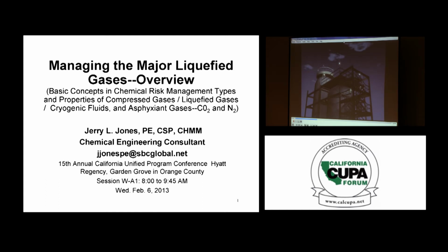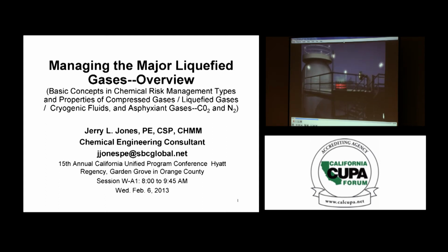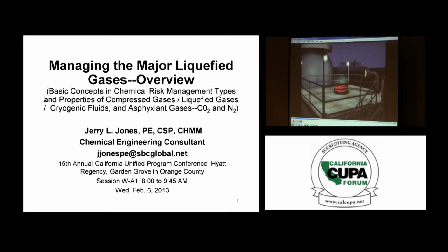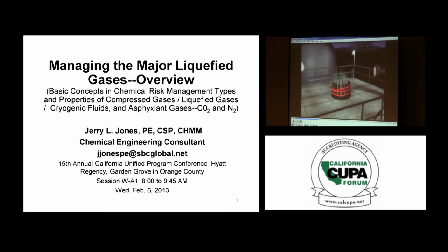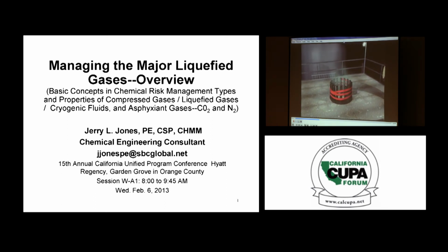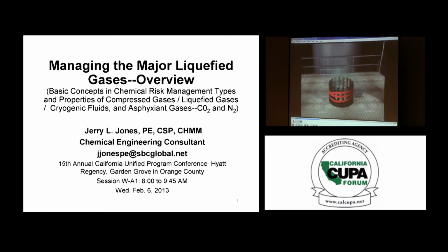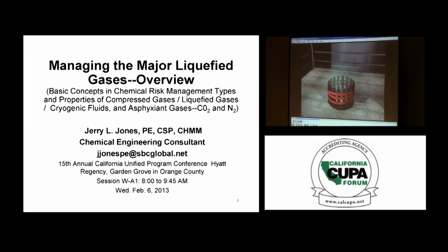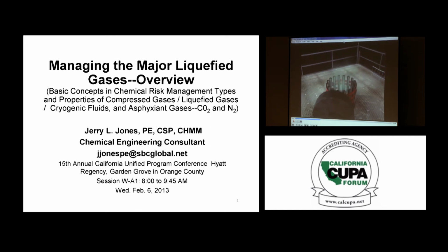Valero's hydrocracker reactor number R1 was shut down for maintenance. A large pipe elbow had been removed, creating an opening surrounded by large steel bolts in the middle of the platform. Workers had wrapped red tape around the bolts and covered the opening with plywood and plastic. Nitrogen flowed into the reactor and exited from the covered opening. Nitrogen is invisible, but it is colored light green here for illustration.